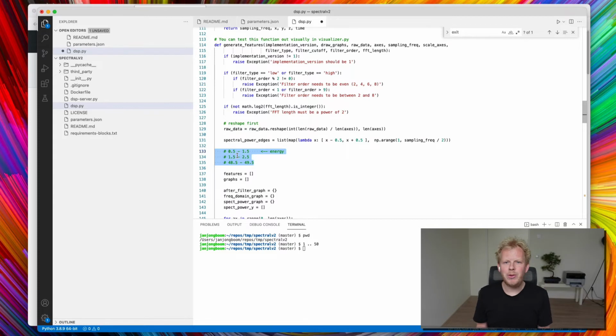This is very straightforward, right? We do an FFT and then we look at the power buckets. But we could just as well do really complex things here. Let's look at features over time. Let's take the derivative of that feature, do all kinds of other filtering over that. Really easy to implement, basically in this Python library or in any other language that you want to go with.